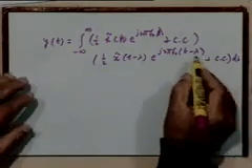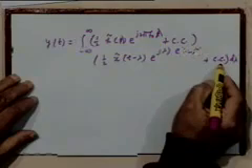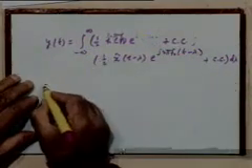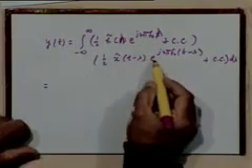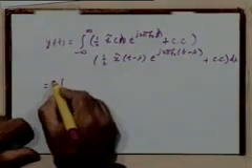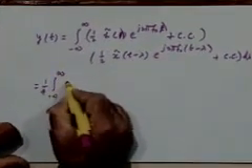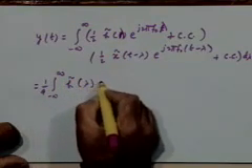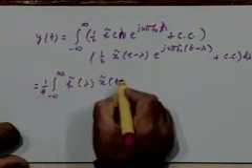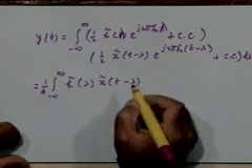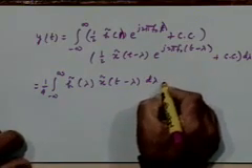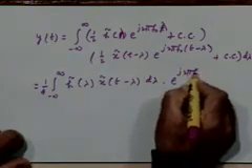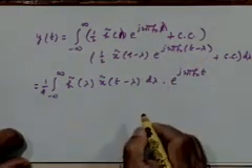Well, the complex conjugate will also contain a half, so that's okay. Now if I proceed term by term, this is lambda here, right? What will be the product of the first two terms? This will be 1 by 4 h tilde lambda x tilde t minus lambda. And what happens to the product of these two exponentials? It is e to the power j2 pi f naught t, because the lambda term will cancel off, right?